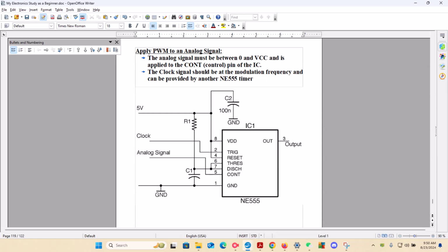And then finally, the last one is it's going through to the VDD, which will output the voltage through pin 3, which is the output. Whatever the output is, whether it's going to ground or to a motor or to something else, that's the output. After all of this, after we've gone through resistor 1 and capacitor 1, we're going to go to ground. Also, our first pin there from the IC will be going to ground.